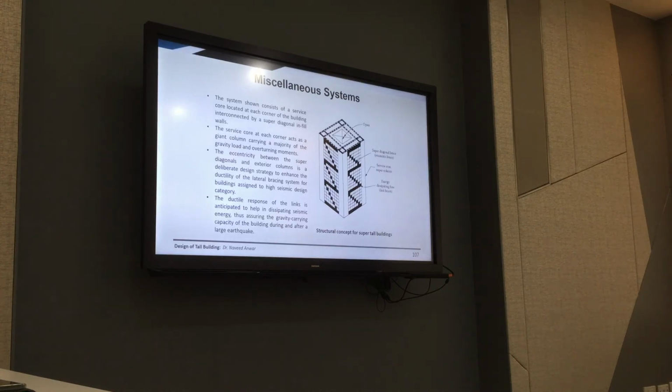Good. When we couple two shear walls together, we need to think that when we combine 1 plus 1, the stiffness should be greater than the sum. Very important. Yes. I learned about the story mechanism, like when the hinges are formed, the building can collapse. Yes, must avoid that. Another is the coupled walls: if you connect the two walls with sufficient beams, we have units, like one will take tension, another will take compression.